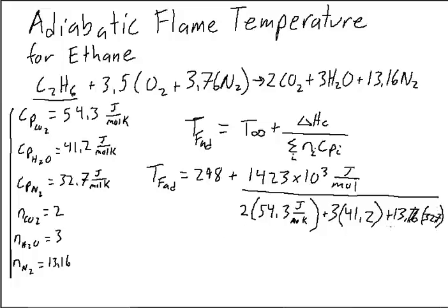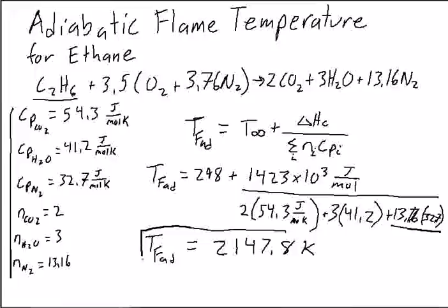So you'll notice the nitrogen adds a significant amount of energy absorption to this particular equation. So T_F adiabatic comes out to be 2147.8 Kelvin. And this is pretty much the maximum temperature that you will see in a combustion reaction.